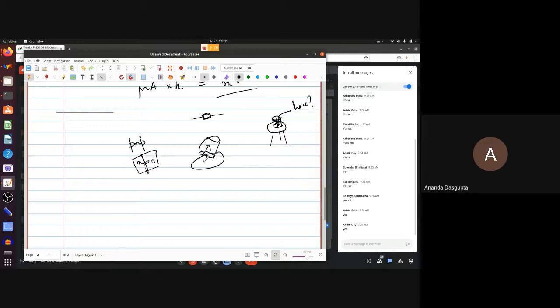I'm asking you to guess. Of course, unless you already know, you would have to guess. So let's just say I've managed to cut this thing and open up the cap. What would you see? Come on, you can just be outlandish and say whatever you want. You see the NPN. That might seem to be an obvious thing. Actually, what you see is nothing. It's air. Inside, there is nothing. It's just a hollow cap.